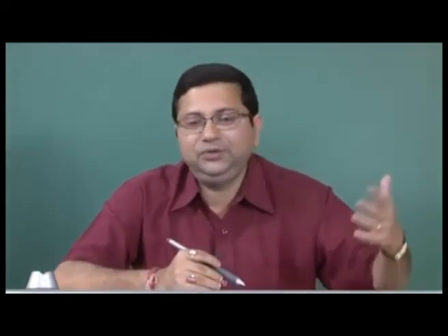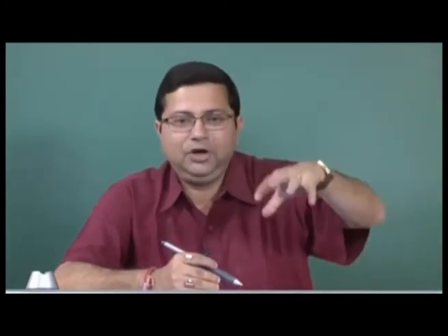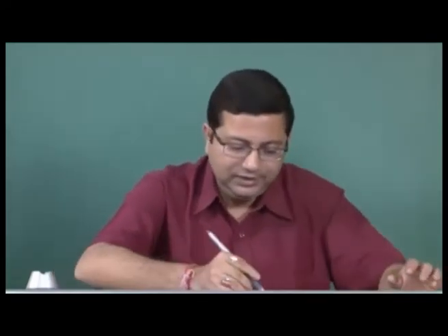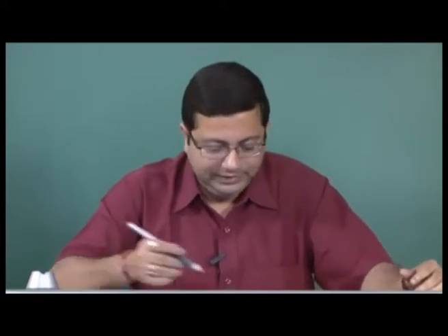And then if you recall, when we talked about the vehicle mechanics, we said that in order to get lateral stability, so that the lift is 0, you need to have the rocket nozzle slightly tilted, right, which is thrust vectoring. Rockets have been using thrust vectoring for more than 100 years now. From the very early beginning of modern rocketry, thrust vectoring was used. So, as you can see here, this is the thrust vector control at the nozzle, and this is a thrust vector actuator which will turn the nozzle about this point. Okay. So, essentially it gives lateral stability to the vehicle.